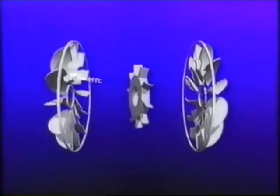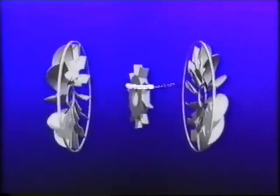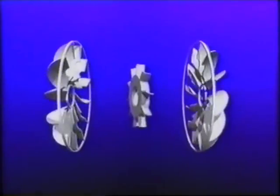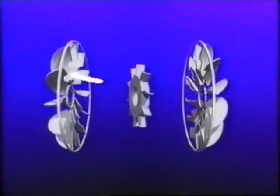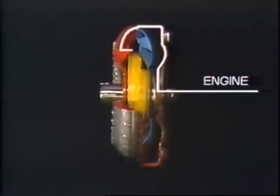The point at which the stator begins idling is called the clutch point. Once the stator reaches the clutch point, the torque converter acts only as a fluid coupling, meaning that it does not amplify torque, but only transmits torque. This shows how the torque converter transmits engine power to the input shaft of the planetary gear.